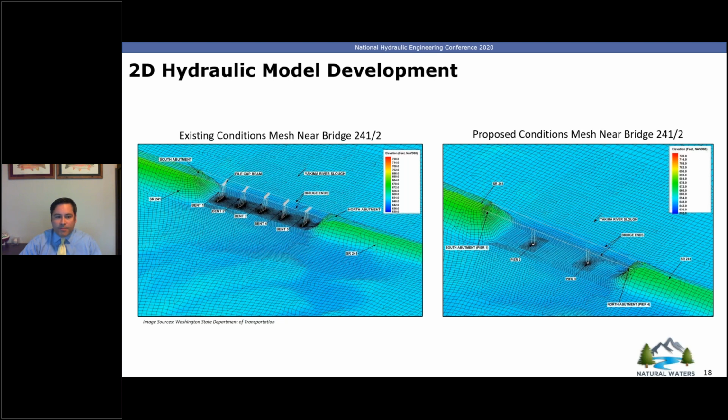I think really the best practice in this case, the reasoning for the mesh looking the way it does is that this mesh was utilized for a variety of hydraulic assessments, one of which included not only the existing conditions with the 16-inch piles, but also the analysis of the temporary work platform. So there was other analysis that really drove the size of the elements and whether you use paved or patch. So following best practices, it really depends on the water crossing.